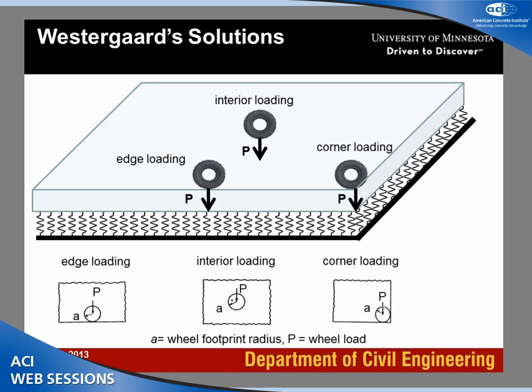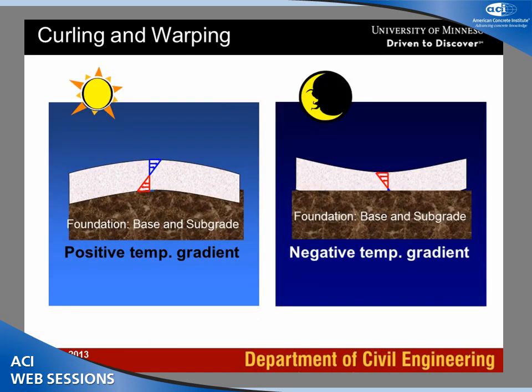So for a long time the best way to improve concrete pavement performance was believed to be just to increase thickness or increase strength. Westergaard also developed a solution for slab curling, and that required characterizing concrete with a coefficient of thermal expansion, but curling hasn't been used in design for quite a while, and even the currently promoted ACPA StreetPave doesn't consider built-in curling. Maybe I don't know the latest version, but I believe up until recently curling was not considered.